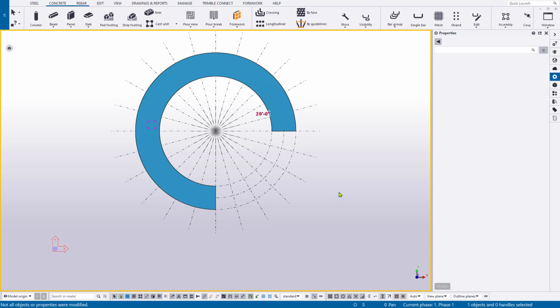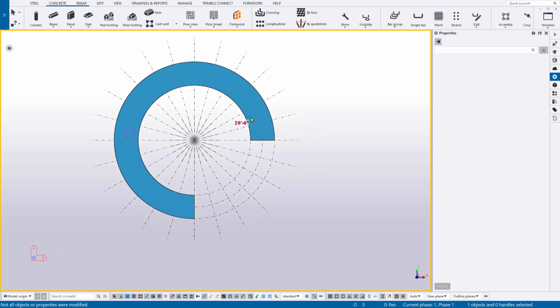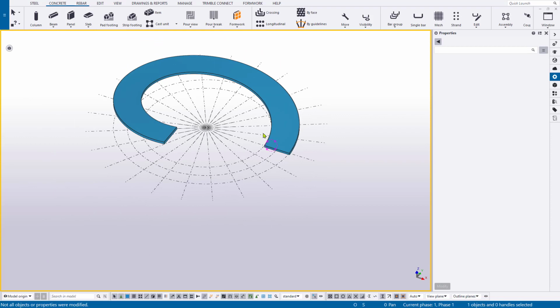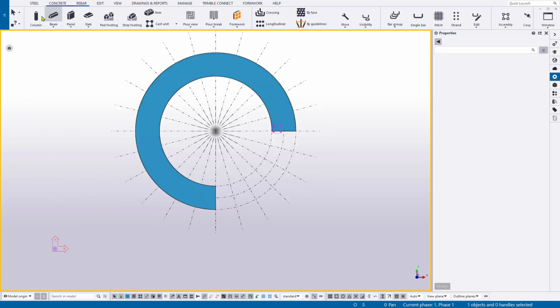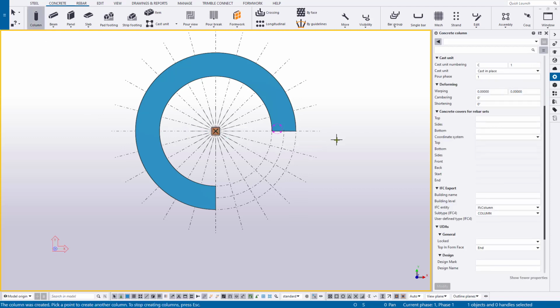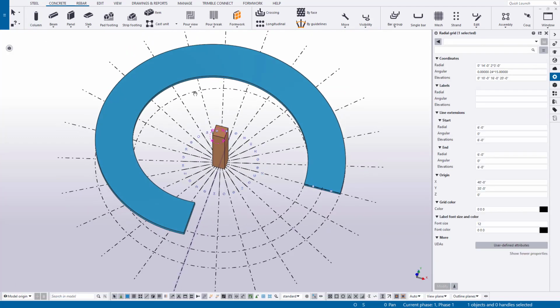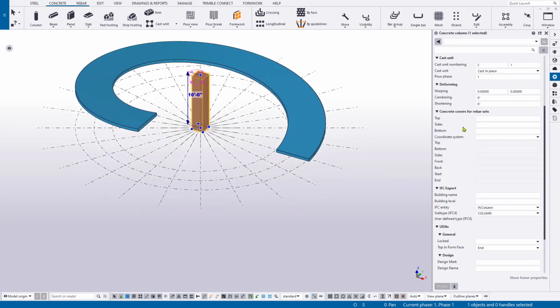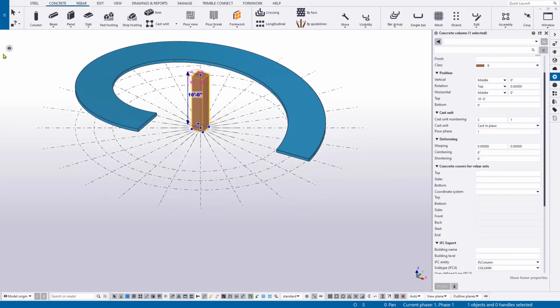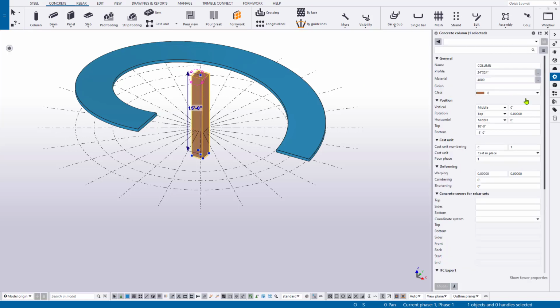I think with this now in place, we can talk about just a couple of other small particulars and things that you may want to take care of when doing ramps in general. Again, whether this is pedestrian or vehicle, you'll probably have some sort of center structure. You can use the column tool to place an object there and control its overall height and depth straight from the properties pane or the contextual menu. We can always do 5 foot. And then we can adjust its profile.